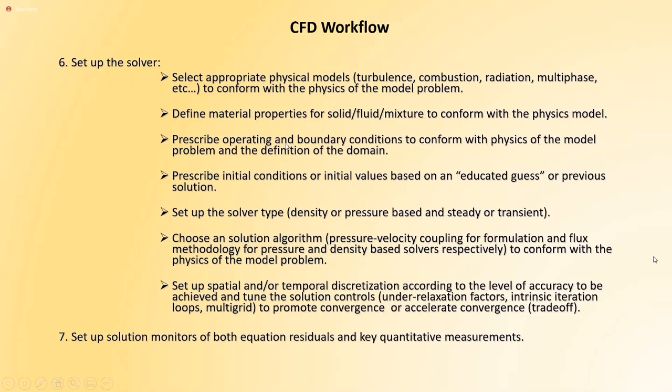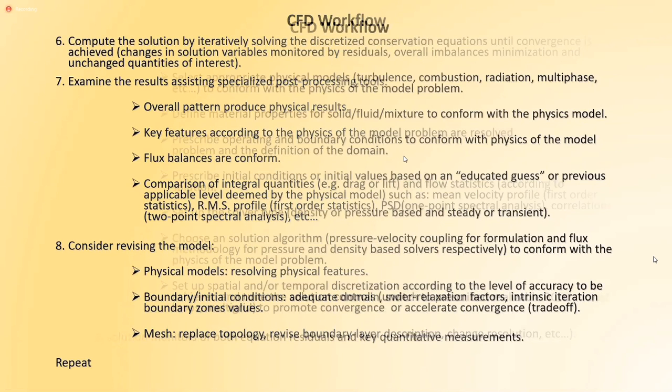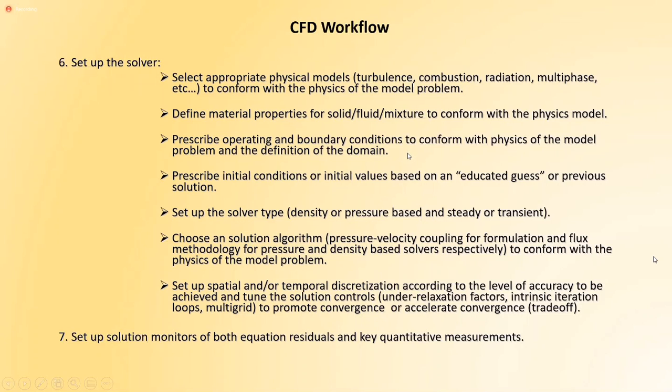Prescribe operating and boundary conditions. I'm very sad to notice that many who do CFD don't even know the difference between total pressure, what static pressure means, and what dynamic pressure means. But that's one thing. Not all definitions of boundary conditions are the same.